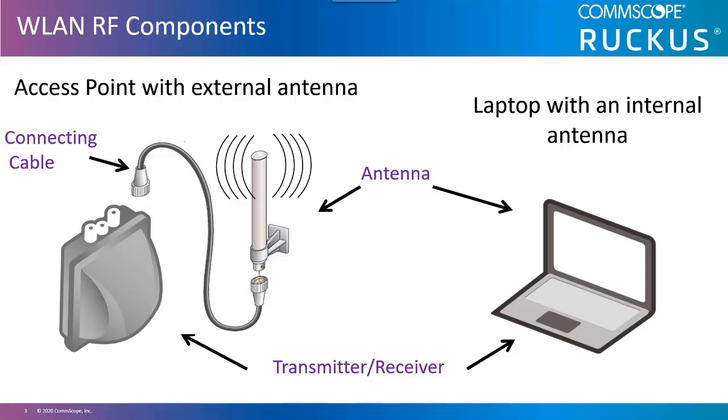The steps involved in wireless transmission are: the transmitter receives the data to be transmitted. It converts the AC signal using a modulation technique to encode the data into the AC signal. Once modulated to include data, it is referred to as a carrier signal, meaning that it contains the data being transmitted. The carrier signal is sent into the antenna for propagation. The signal is sent out of the antenna at a configured amplitude or power level based upon the properties of the antenna.